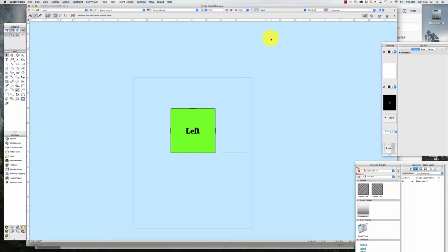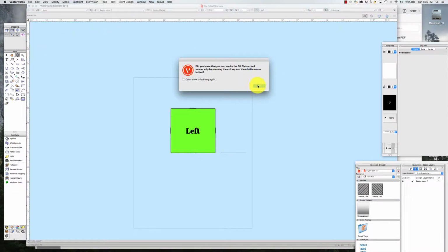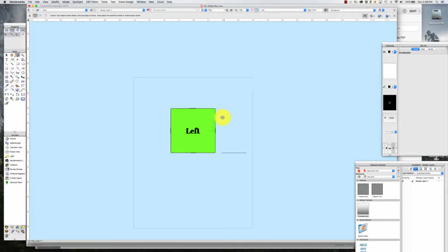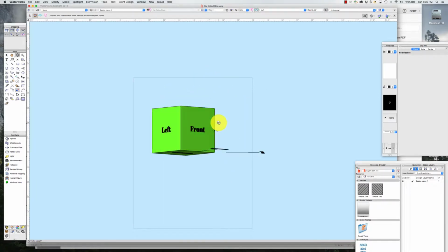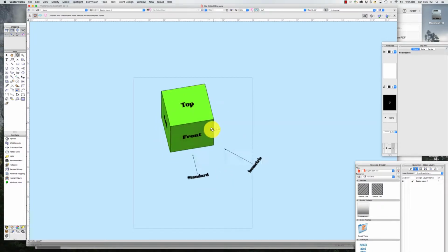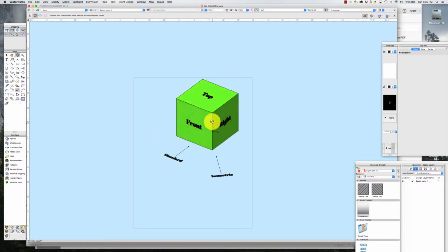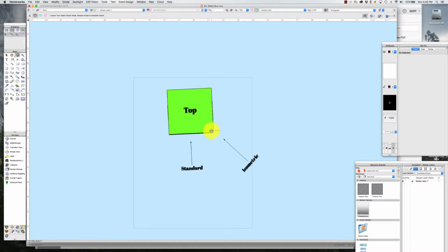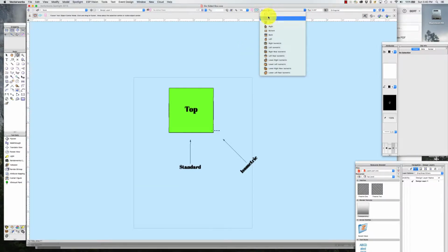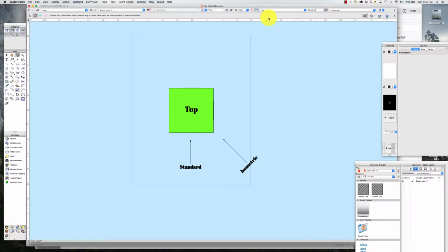there, and left. You also can use this tool, what's called the flyover tool. Did you know you can invoke that? I did. To rotate around an object freeform. So if you're trying to get a good look at something, you can use the flyover tool to just rotate around it. But if I rotate it so that I'm in top view, and it looks like I'm in top view, but if I want to make sure I actually am mathematically in top view, because you'll notice here it says custom view, I have to actually switch to top, and it will look directly at the top.